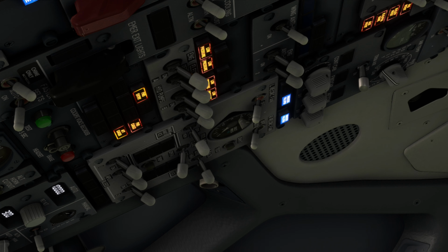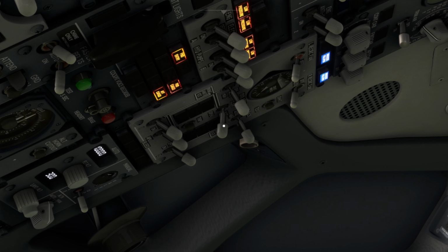Obviously, when an airplane flies at high altitude, the ambient atmospheric pressure will drop, and above 10,000 feet, it starts to drop below levels at which normal human function can be withstood. Therefore, we have pressurization on airplanes, and this is something that started to come along during the Second World War as bombers in particular started to fly higher. And the crew started to report the effects of hypoxia. So we've got ourselves a pressurization system on all modern airliners, allowing us to operate at altitudes well above 10,000 feet.